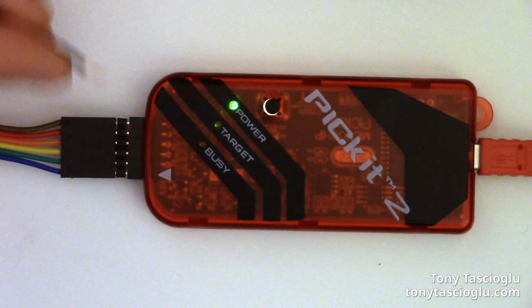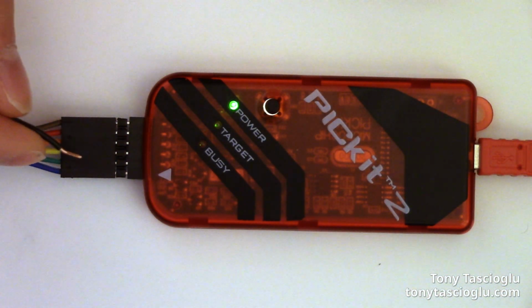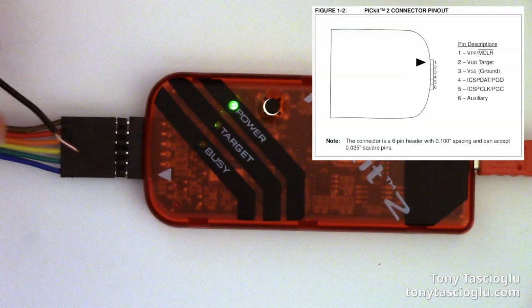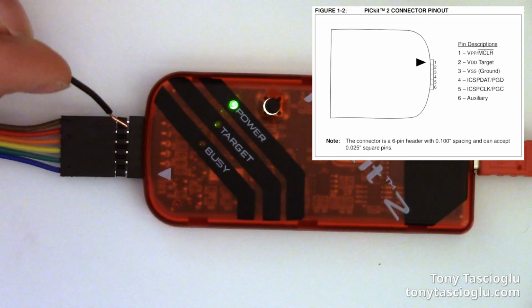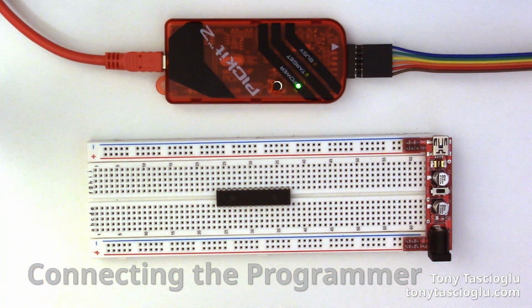As for the PICkit, you will notice that the PICkit has 6 pins on its output. The pin that is right by the arrow is pin number 1, so it goes 1 and then down through 6. Now we can begin to match the pins from the PICkit to our IC of choice.